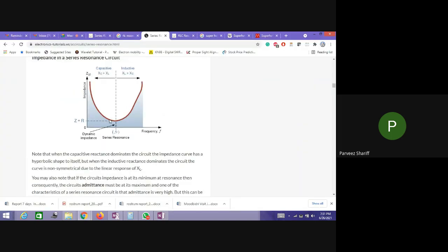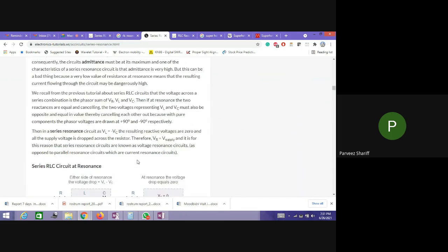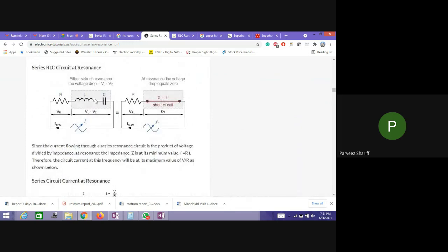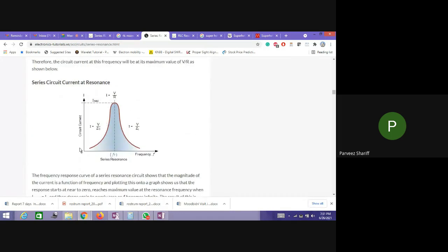So as you can see here, what is left in the impedance is only the resistive value. The inductance and capacitance act like a short circuit at that particular frequency. Now we have only the resistor. This is the current chart that we will get, what I had written before. So I is equal to V by R, so it depends on the voltage and whatever the resistance value.